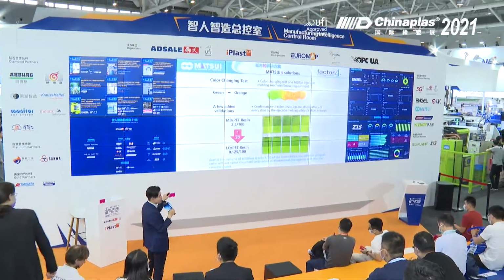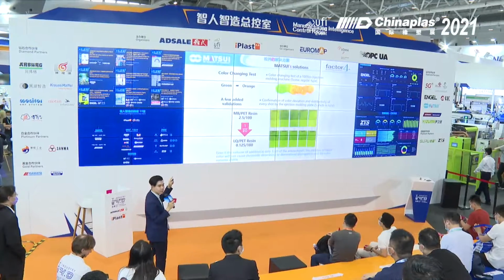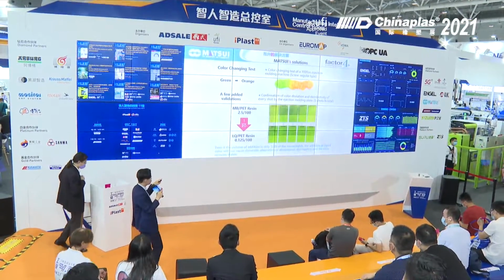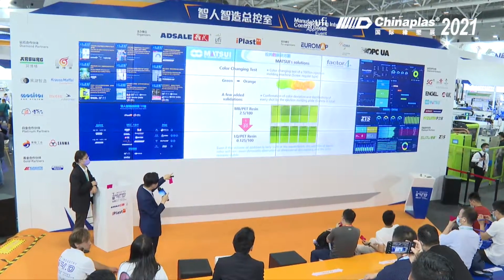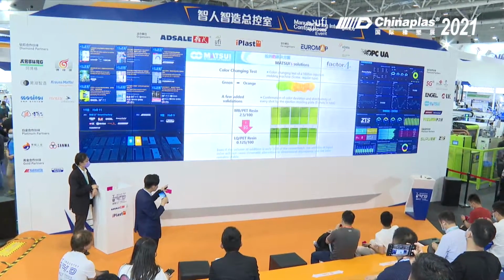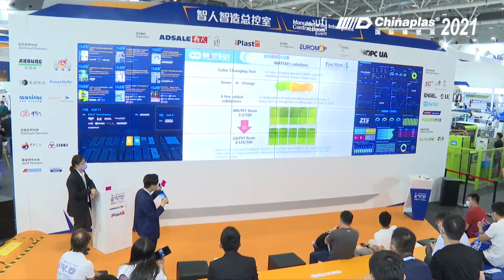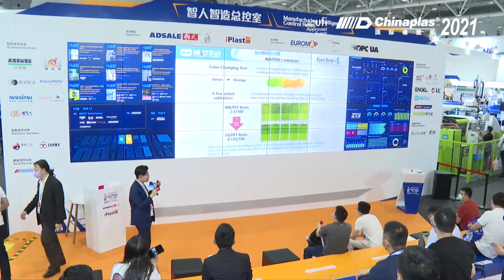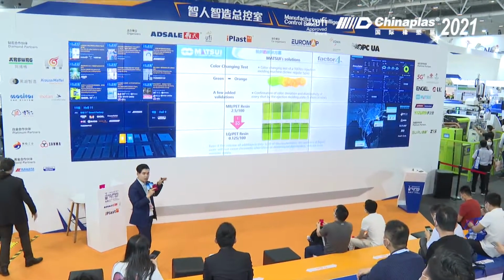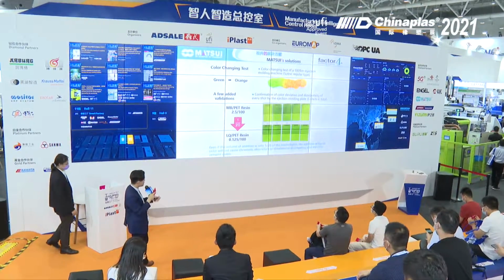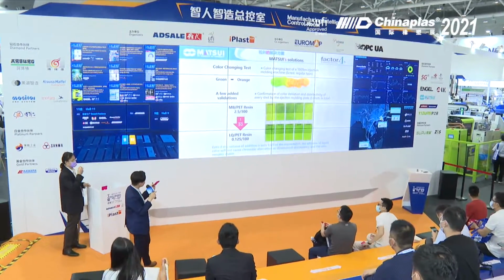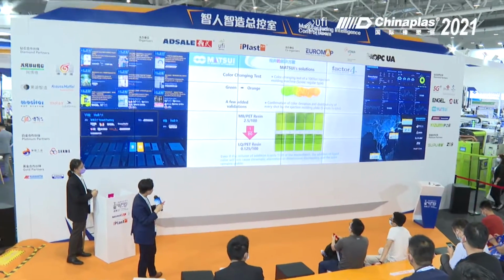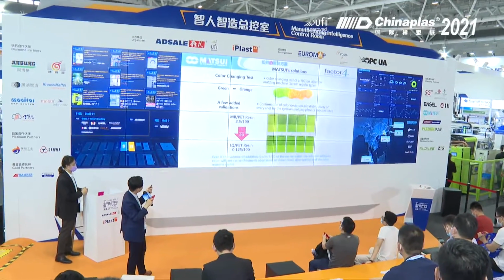We use the ink jet compared with master batch, and we use only 5% volume, which will not cause chromatic aberration or dimensional discrepancy, because the ink is very well dispersed, for materials like PP or PET. So we do not need to use additional master batch. So it's a very big piece.